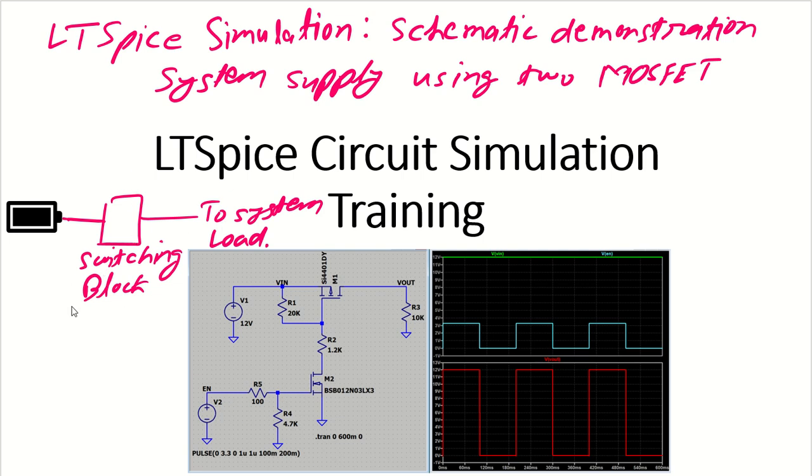It is a switching on, switching off circuit which will make sure that whenever the system is not working, the system is not draining the power from my supply source, that is from my battery. So it will be totally cut off. And whenever there is a need to give a supply to the system, there will be a switching action here, and this is how the battery supply will be connected to the system. This is why it is called high side switching.